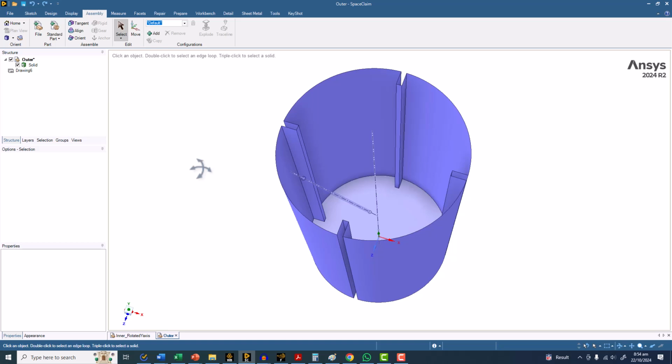domain. So the problem is that if we made the geometry of the impeller from scratch and we had just changed the orientation, then this would have been easy. But now because we already made a domain, we have to align the domains to each other. Otherwise, where the inner domain is in the tank will not be at the location after moving the inner domain from its original position where we made both domains.